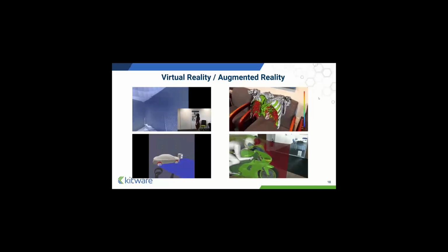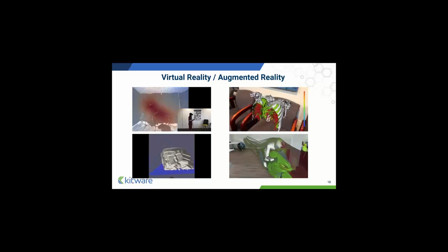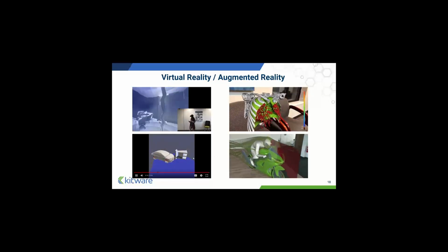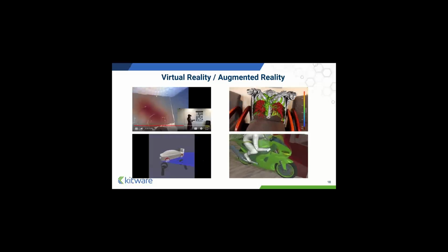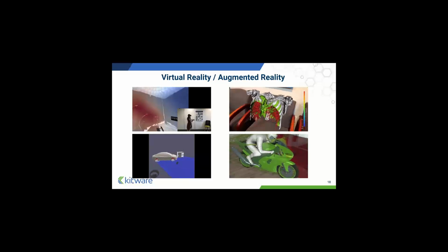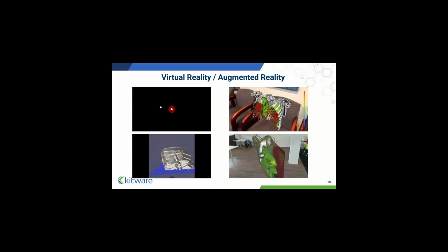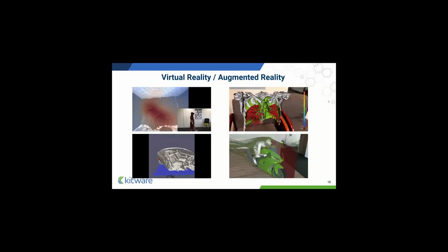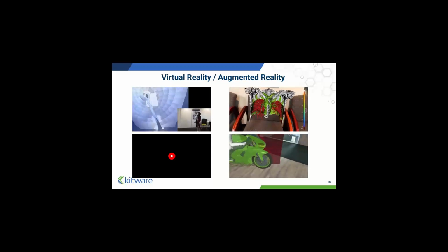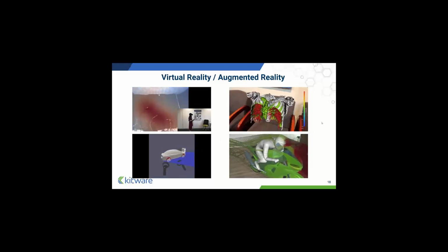just the post processing, I can showcase you can do very easily some AR and VR in ParaView. Below, this is some OpenRadioss simulation visualized by Sébastien Villeneuve using ParaView and VR. We have some acoustic measurement here on the top, and some augmented reality with some medical imaging and some CFD simulation with the OpenFOAM motorbike. It's very easy in ParaView. You have to prepare your scene as we did, and just load the right plugin, click one button, put your headset, and that's it. You are working inside your car crash, or your cell drop.